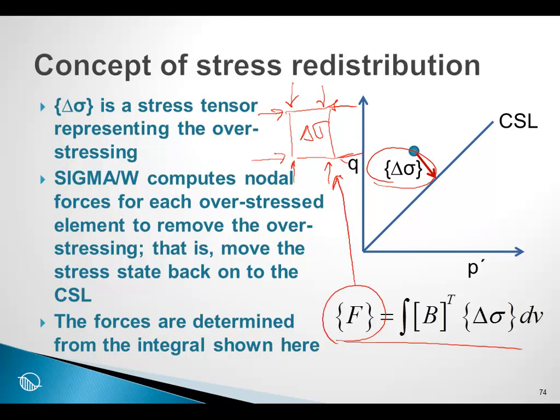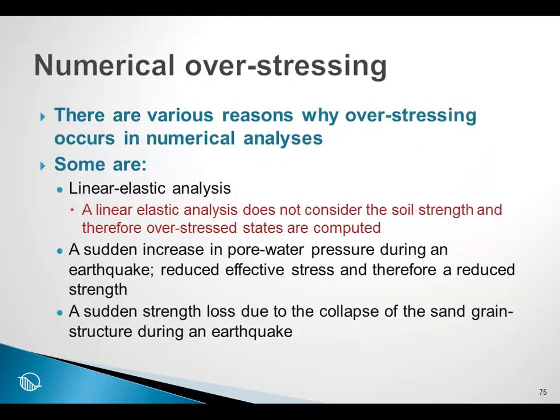When we apply the forces, the stress is reduced in that particular element, but it means that the forces on the nodes of that element result perhaps in stress increases in neighboring elements. So this is a pictorial summary of what we mean by a stress redistribution.